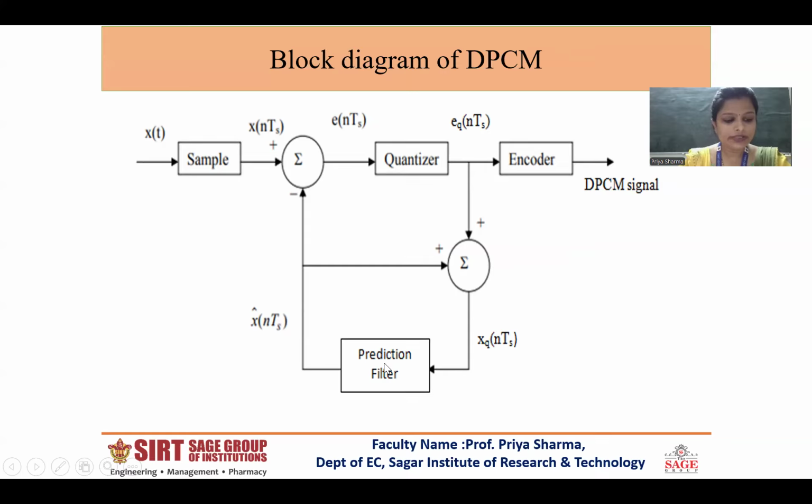An integrator determines it and applies it to the differentiator for comparison with the input signal. Then it is convenient to find whether the next difference signal needs to be positive or negative, and of how much amplitude, in order to bring the accumulated signal level as close as possible to the input signal. At each sampling time, the difference amplifier compares the input signal level and the accumulated signal level.